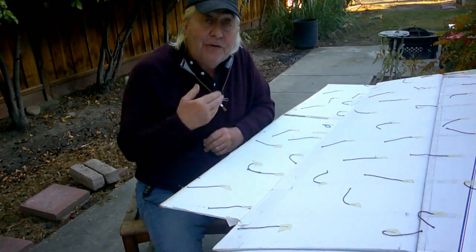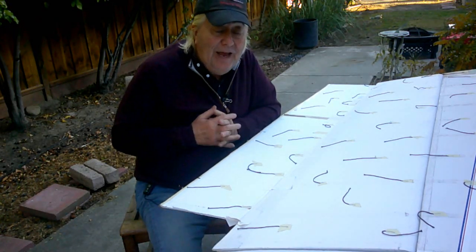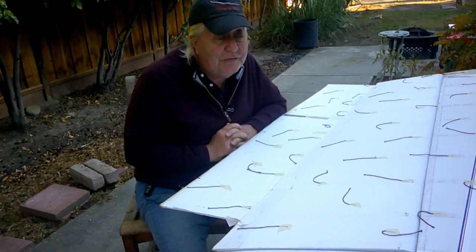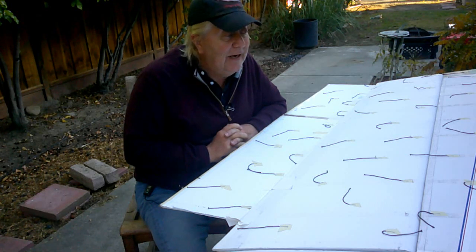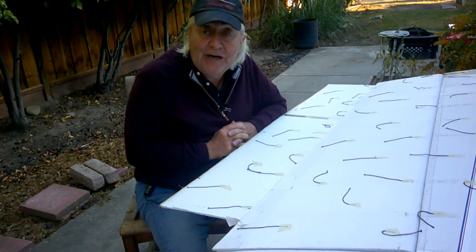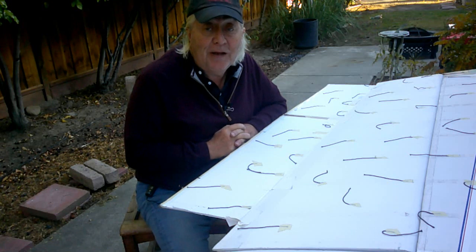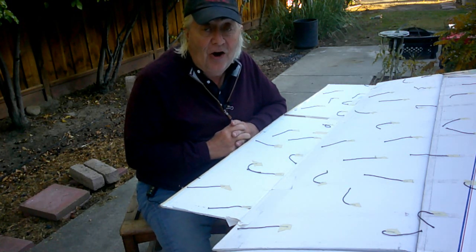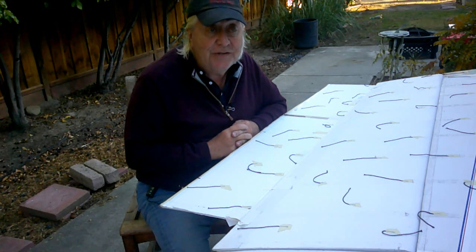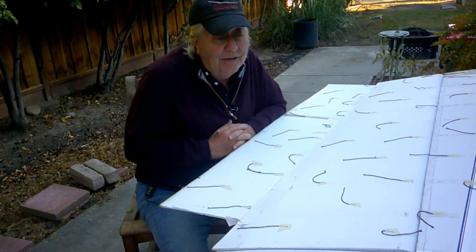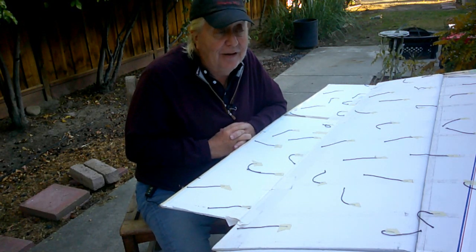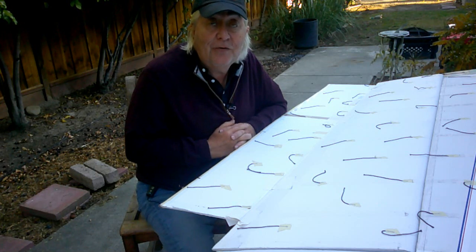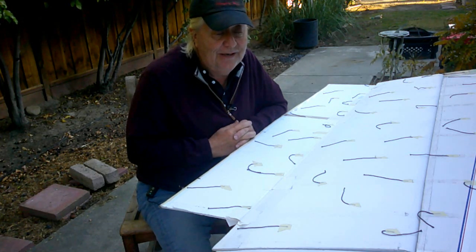So it looks like right now that the better way to design a foot-launch flying wing, rather than saying I want this much span, I want this much wing area, is to say, okay, I know it's going to weigh about this much, and we can just say 300 pounds, because your airframe is going to weigh 100 in round numbers, and your heavier pilots are going to weigh 200 pounds like me. So 300 pounds. And I need a certain amount of lift to get my wing off the ground at a reasonable speed, like 20 miles an hour.